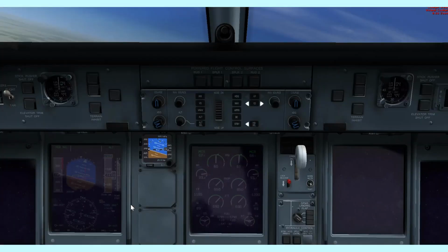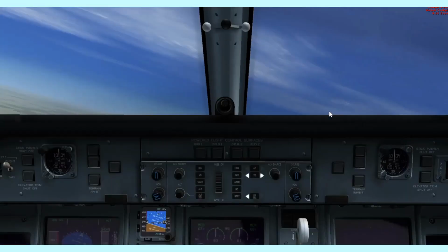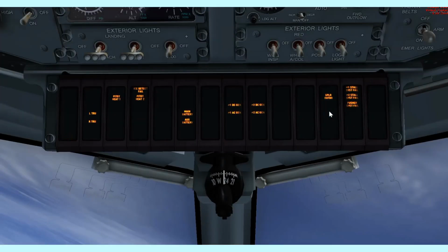Of course, you'll have all these lights flicking here and there, which will cancel once everything overhead comes up here. So very important. Here we go. You can see it's depressurizing. The cabin is depressurizing, so you've got a cabin pressure light coming on as well, telling you to don your oxygen mask and prepare for a drift down to a low altitude, 14,000 feet, because you're going to depressurize. And that's basically about it, guys.